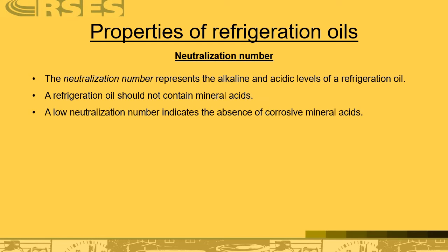Neutralization number. The neutralization number represents alkaline and acidic levels of refrigeration oil. A new refrigeration oil should never contain mineral acids. A low neutralization number indicates the absence of corrosive mineral acids.